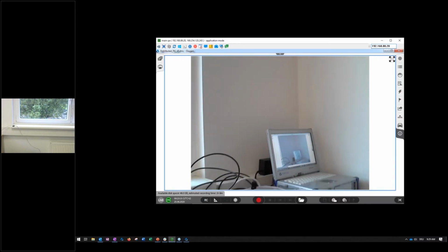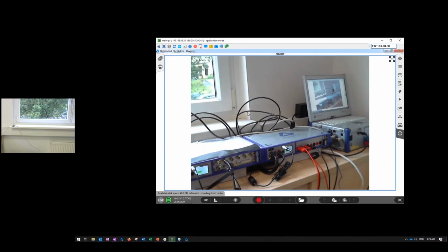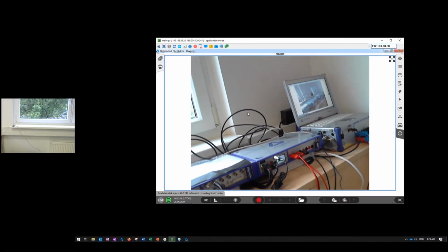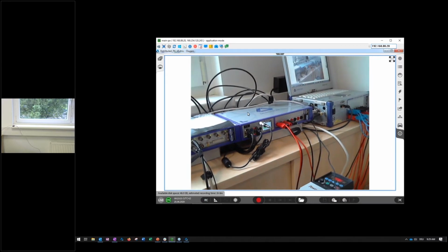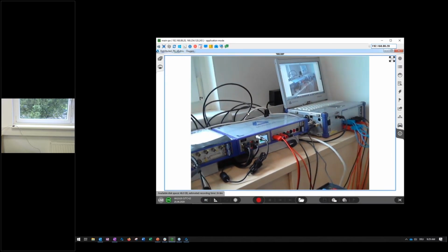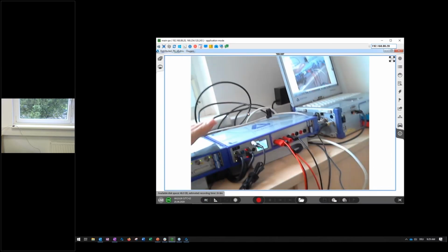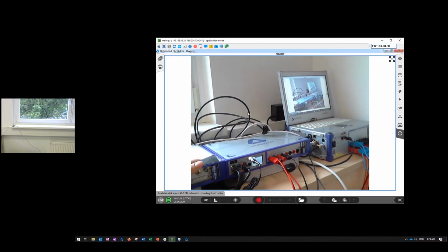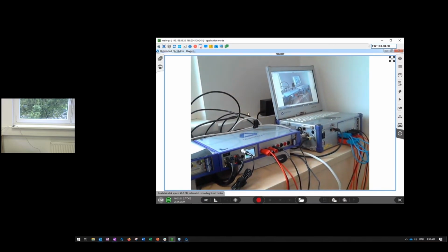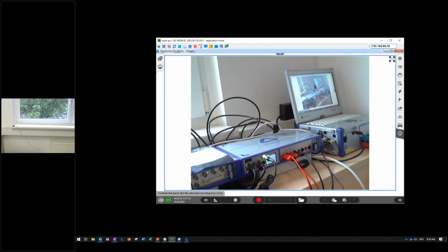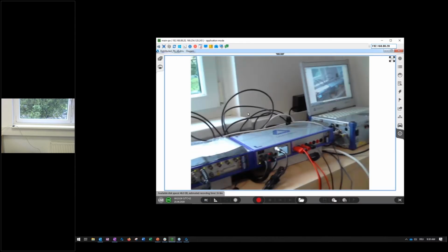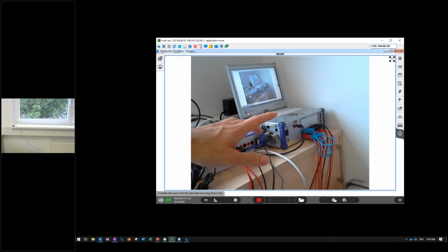Now, when you see this here in the office, it is not necessarily a distributed power analyzer, but more or less a local power analyzer. But please imagine that between all these measurement units, there can be a distance of up to 100 meters, because the data is transferred over LAN from the front ends to the main measurement system, to the base unit power analyzer.